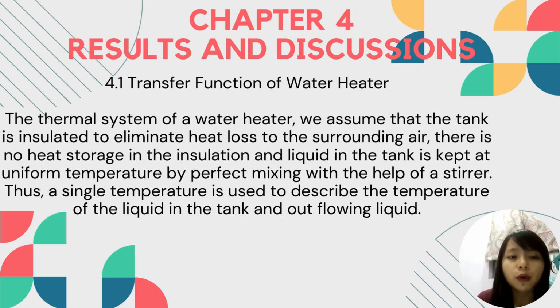4.1 Transfer function of the heater. For the thermal model of the water heater, we assume that the tank is insulated to eliminate heat loss to the surrounding air. There is no heat storage in the insulation, and the liquid in the tank is kept at a uniform temperature by mixing with the help of a stirrer. Thus, a single temperature is used to describe the temperature of the liquid in the tank and in the outflow.